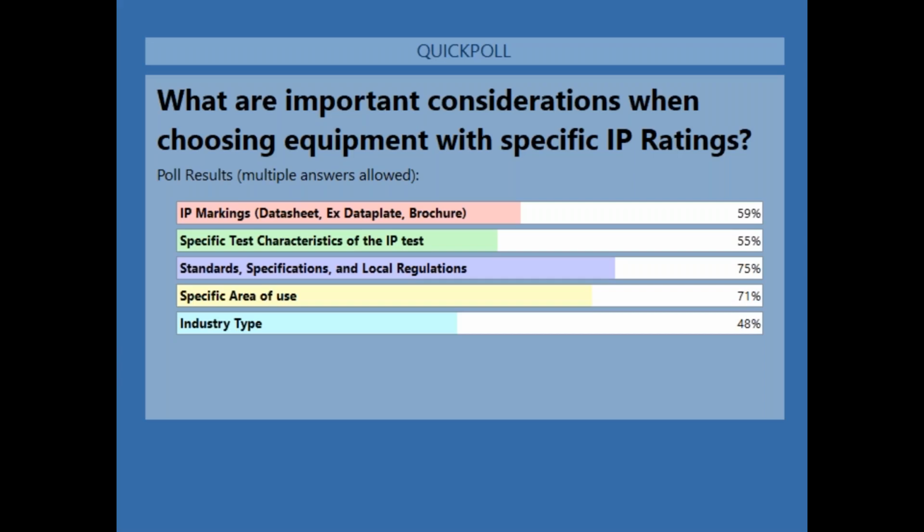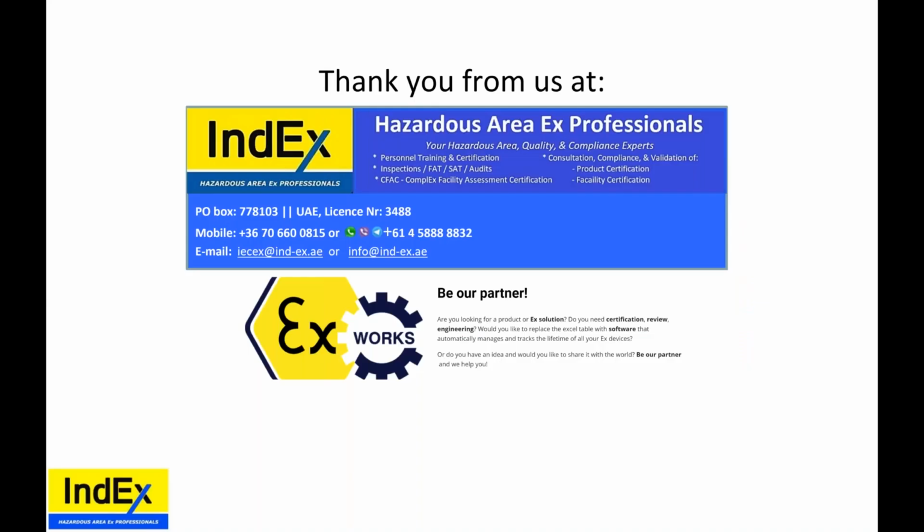While the simple apparatus would fall under the minimum IP requirements that the specification, usually by the EPC or end user, calls for. Usually IP54 minimum. Nearly all EX protection techniques are minimum IP54. EXP is IP44. EXE with insulation on terminals and other things is IP44. Yes.